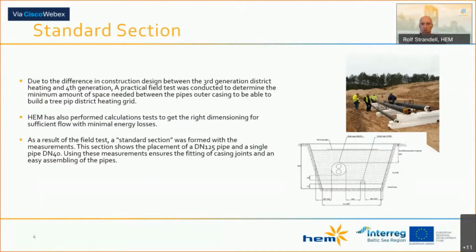And to do that with 3 pipes is a bit difficult, because you also need to go up and down sometimes. And there are no ready-made pipes with 3 pipes with insulation. So we need to place this third pipe somewhere. And this third circulating pipe is a little smaller pipe.